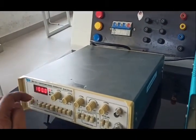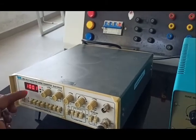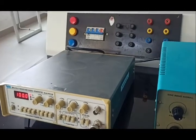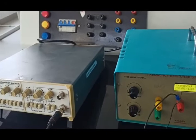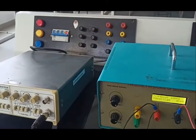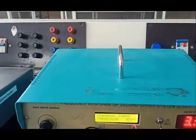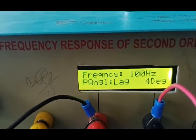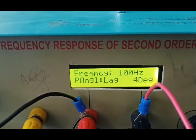So this is the first trial reading wherein you need to tabulate for different case studies. For the first case study, we have set R equal to 1k, and L and C remain the same, that is L is 103 microhenry and C is 0.1 microfarad. Okay, so for 100 hertz you can record the frequency, it is 100 hertz, and the phase angle for the second order system is 4 degree.